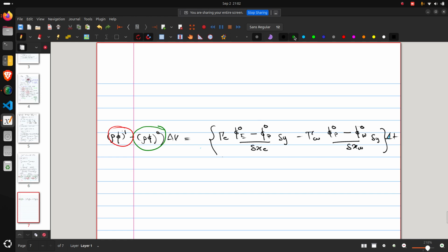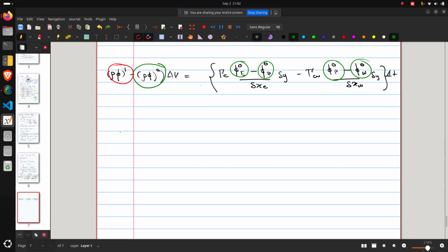And we already know all these values, right? And the only unknown is this phi 1. So we can straight away get the values of phi from all these known values, right? So this is a simple algebraic equation. We won't get a linear system of equations. So we can straight away get phi 1 as a function of all phi i's at some known values.